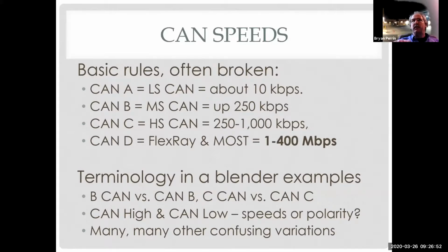And MOST is media oriented system transfer or something like that, but media is in the name of MOST. It's specifically around infotainment. The book talks about Ethernet, which is a similar protocol to what we use in buildings. Some manufacturers are playing with Ethernet, but it's interesting, MOST is still gaining popularity. Honda actually went with a MOST network instead of an Ethernet network.